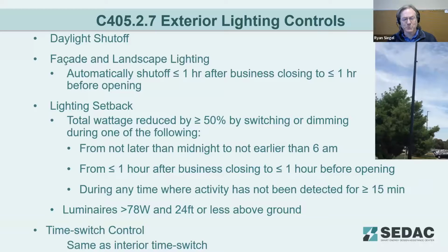So time switch controls. So again, we've got to have daylight shutoff and time switch controls. The reason for having both, particularly as we've moved to LEDs, is these are more expensive and heat during the middle of the day is the most damaging to them. So we want to make sure that they do turn off. So in case that daylight sensor fails, the time switch is going to be a good backup for you too.